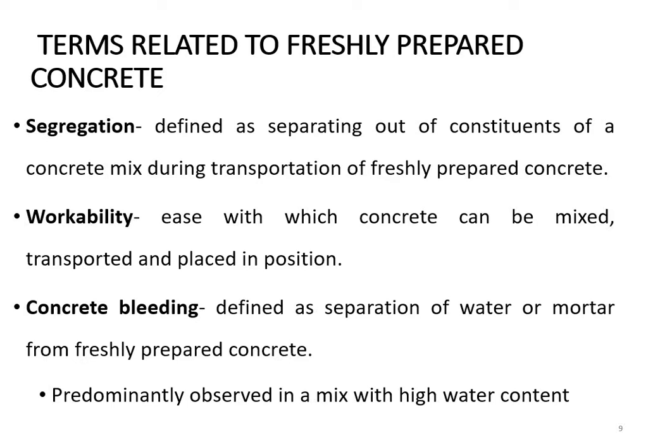Second one is workability, the ease with which you can mix the concrete, transport it to the required place, and place it in position. Generally workability increases with the increase in water content. If the water content is more, then it is more workable. You can work on the mixture more easily.